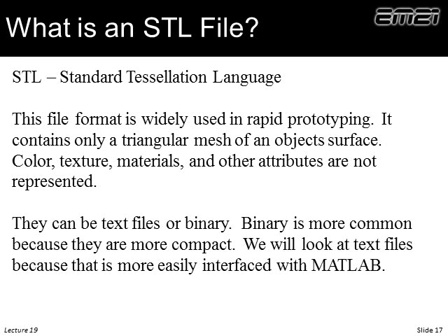Okay, so now we are masters of text files and manipulating strings in MATLAB. On to STL files that we will read and save as ASCII STL files, or text STL files. So what is an STL file? It stands for Standard Tessellation Language. We have some 3D object. Imagine meshing its surface with a bunch of triangles. The STL file is simply a list of those triangles, nothing more.